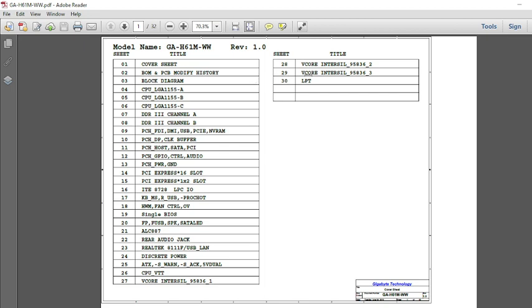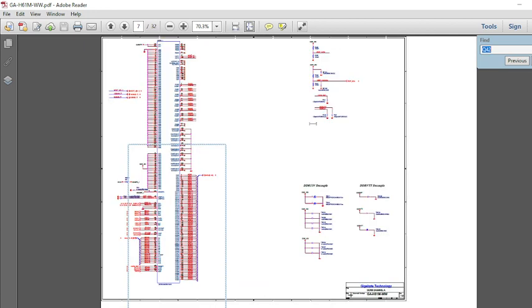For starting with the RAM section, I don't have any kind of board view for this, but I have the schematic, and I don't have any kind of photo. But we will start with our part number, meaning I have the MOSFET number, and from that we will find it. Let's start with the RAM section. Q42 is the MOSFET which is connected in the RAM section.